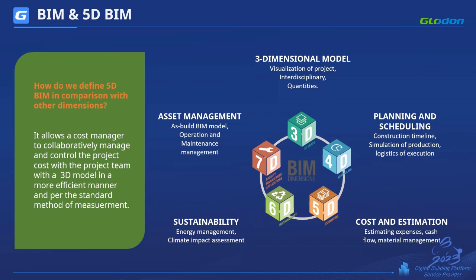Okay, if you have MS Project software or Primavera software, you can create a construction plan out of it. Then if you have a Revit model, you can synchronize that construction plan with your Revit model by using Navisworks software. There are plenty of other software available like Bexel Manager, Synchro Pro. Then you can create a 4D simulation.